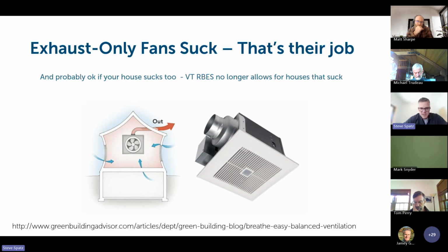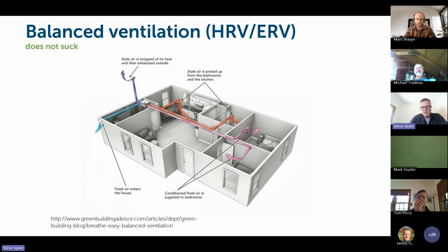And we've always talked about the detriments of where that supply air or fresh air, quote unquote, is coming from. But also, housing that is being built now under modern codes, the air tightness requirements are minimizing the amount of infiltration we're getting through the building in the first place. So the tighter the house, the less effective exchange you're getting. So exhaust fans in an existing home are still going to be the typical go-to method for meeting the ventilation requirements. Be considerate, though, of what type of fresh air exchange is going to occur in that home when using that type of equipment.